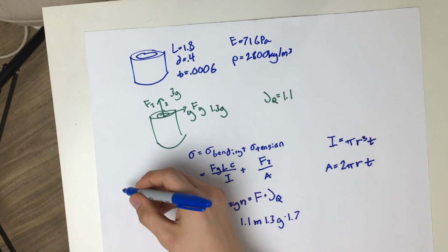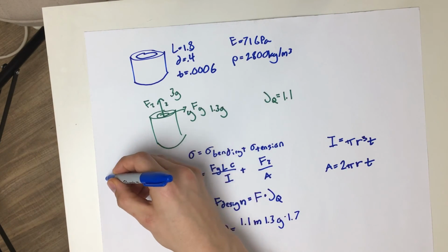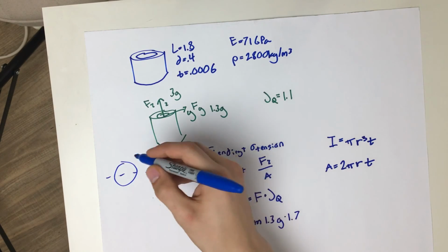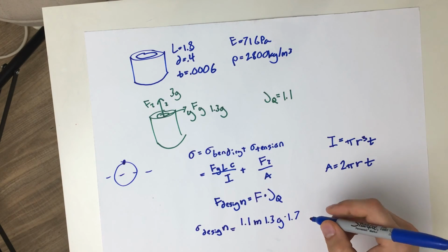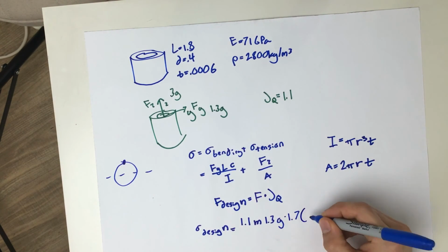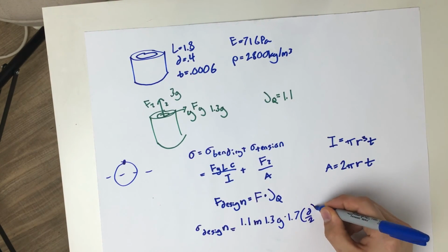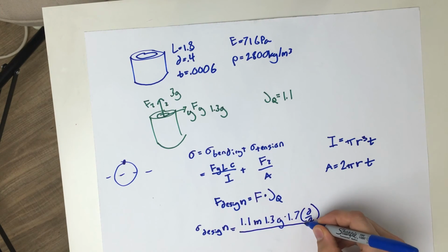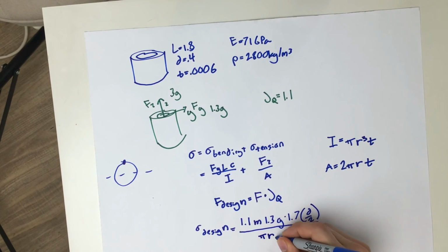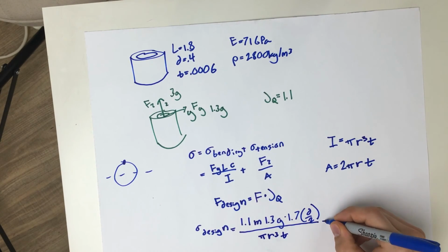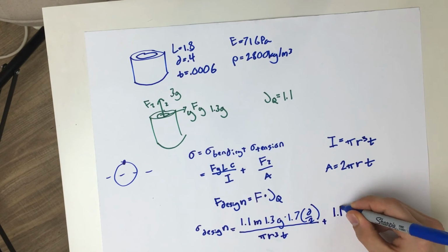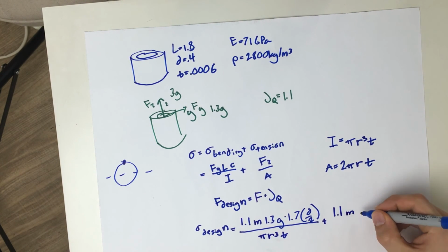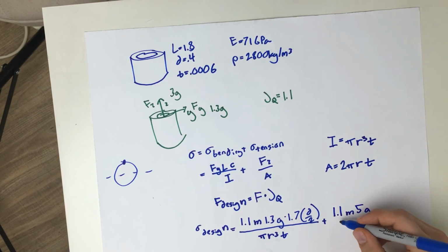the neutral axis, if you were to just make the cross-section symmetrical, the highest bending stress is going to be, of course, right here. So that distance is the R. Okay, moment of inertia, already did that. Finally, same thing we just did. Design load factor, mass times 5 G's. Okay, area.